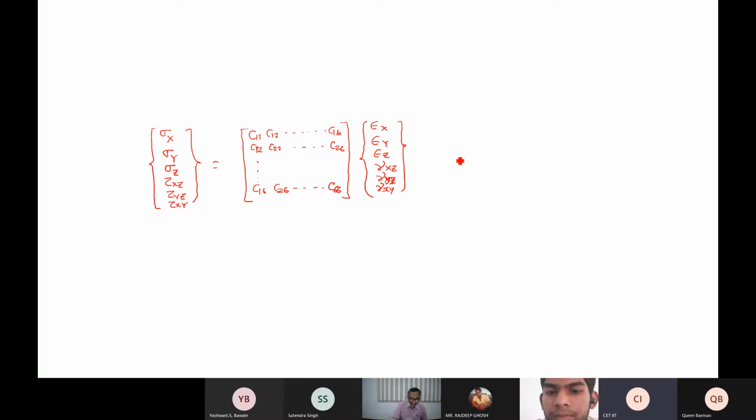Now, before going to orthotropic, I have given some idea of what this is exactly. It comes from the generalized Hooke's law, where the 6 components of stresses can be expressed as a linear combination of the 6 components of strains and vice versa. But before that, you can physically see what exactly the elements of this matrix are. Suppose this is your X, Y, and say Z.